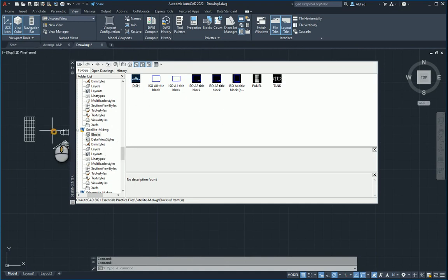So I've got my blocks, and maybe that's all I need. Maybe I can go to another drawing and grab blocks that are sitting in there into that. So you maybe have all your furniture blocks in one drawing, all your window blocks in another drawing, all your bolts or your nuts in another drawing. It doesn't bloat up your main template that you're using. And then by having all those drawings in one location, you can use the Design Center to go to those drawings and pull in the blocks that you want.